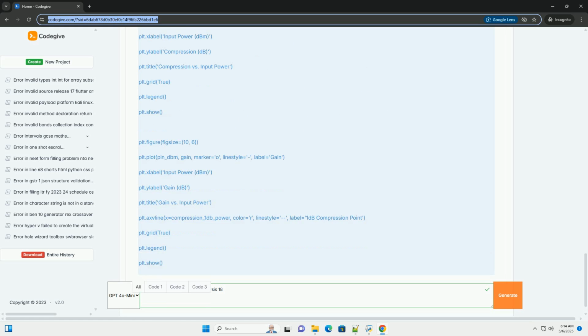8. Nonlinear circuit behavior. Understand the circuit. If you're analyzing a highly nonlinear circuit, for example a mixer, make sure you understand how the signals are supposed to mix and which output frequency you should be measuring. Filter appropriately: use filters in your simulation setup, or in your measurement setup, to remove unwanted harmonics or mixing products that can interfere with your measurements.